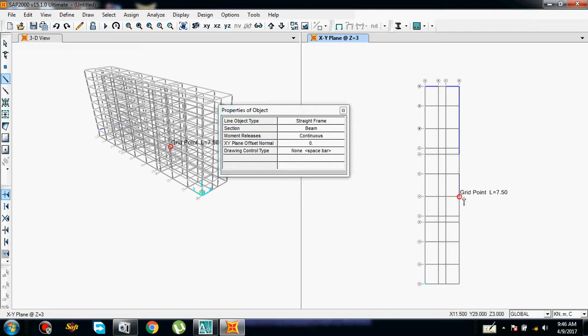Don't get annoyed that you should not have to do all this grid. You should not model all this grid. It will take years, not actually, but hours to do that, and it will be very boring and frustrating to do that. So I have a shortcut here. I will model first floor, beams and columns, and finally replicate it to all floors.